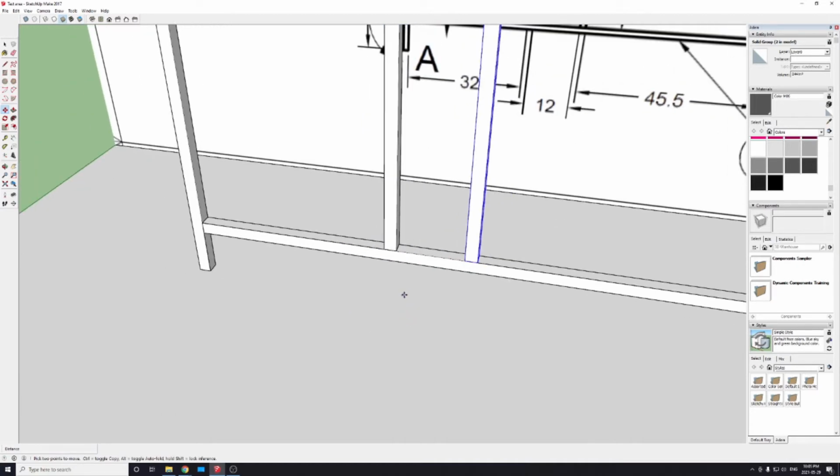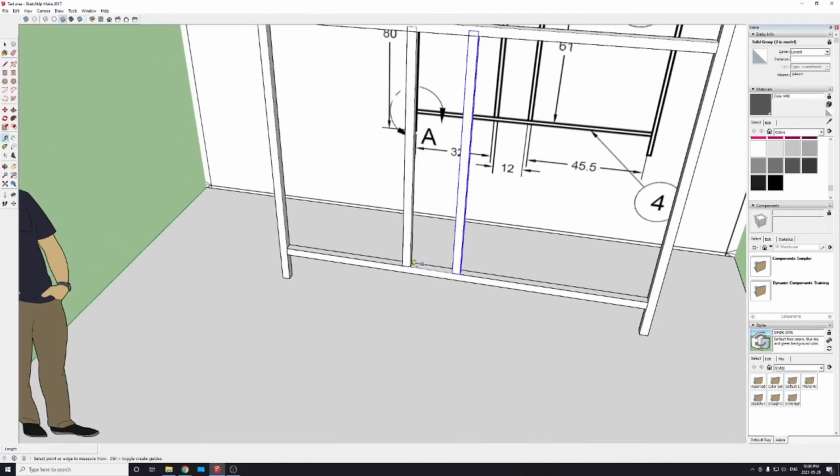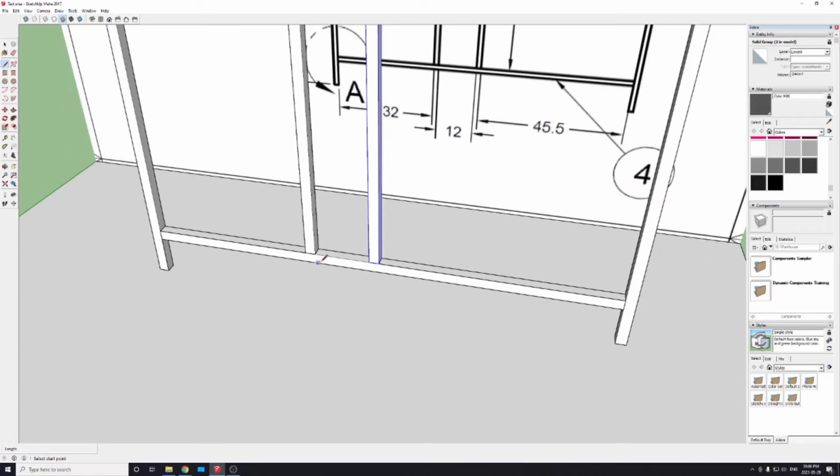Just to make sure, because per IPSC rules, this gap here needs to be a minimum of 12 inches, let's take our tape measure tool and verify. What does that say? It's 11 inches. Okay, so my measurements are right out to lunch. But I'm pretty sure if I pick the line tool again and just hover along this line, it'll snap to the center of this. Whatever line that you're hovering over, it'll find the center of that just by hovering over it. It says midpoint and group.